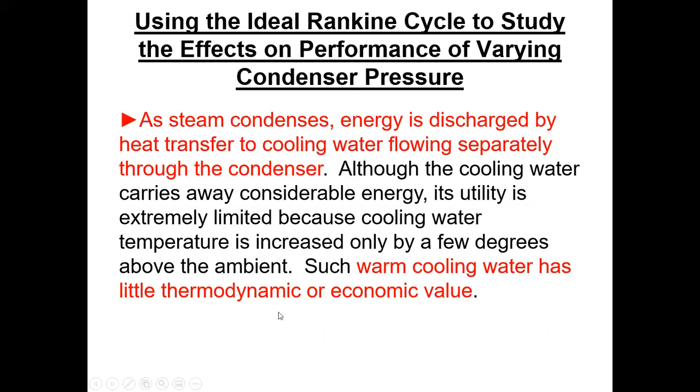As steam condenses, energy is discharged by heat transfer to cooling water flowing separately through the condenser. Although the cooling water carries away considerable energy, its utility is extremely limited because cooling water temperature is increased only by a few degrees above the ambient. Such warm cooling water has little thermodynamic or economic value. And we talked about that some.